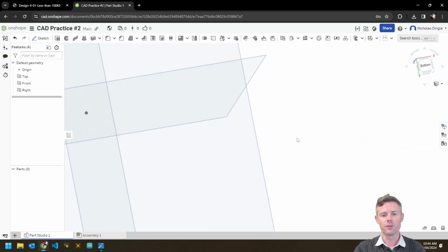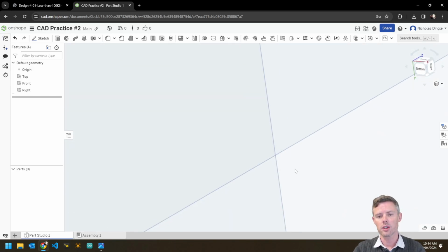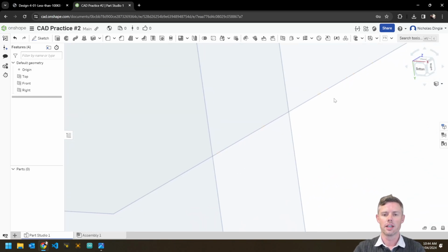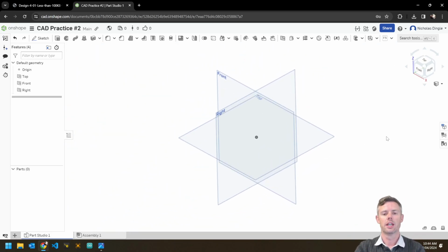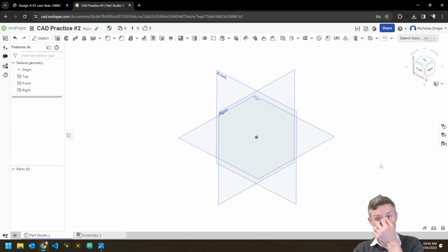And if you find yourself really crazily lost like I do sometimes, what you've got to do is find a white patch in your 3D model, right click anywhere and go isometric. And it goes back to that default isometric view. Okay. The other thing you can do for navigating as well, guys, is using this cube widget up here.